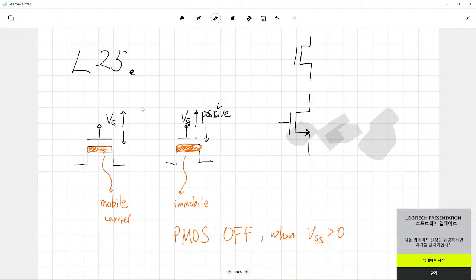Then where do we have a source? This one or that one? From the viewpoint of the structure itself, there is no difference between source and drain. Actually, MOSFETs are symmetric devices. So the only difference between source and drain is whether some part is biased with a lower bias or a higher bias.